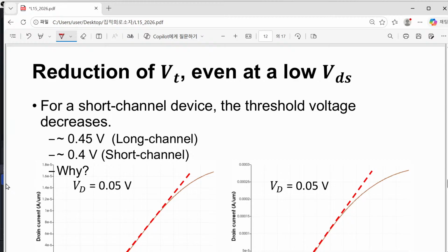Second, you have to understand the behavior of a long channel MOSFET, and that is well given by the Pao-Sah double integral. And third, channel reduction is stopped by this effect, reduction of VT. That's all. And we must solve this problem. That's all for our entire semester.